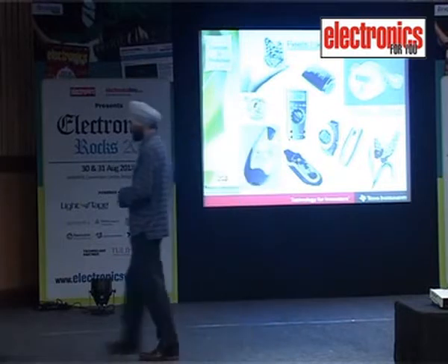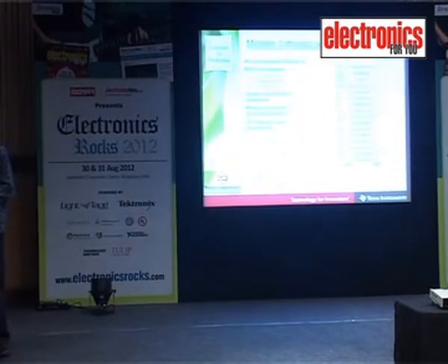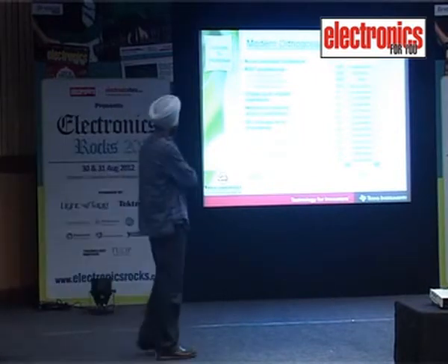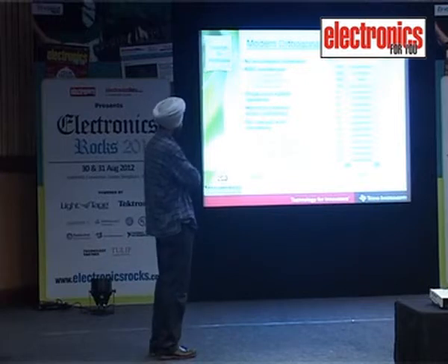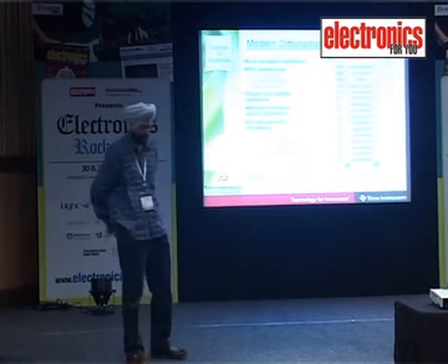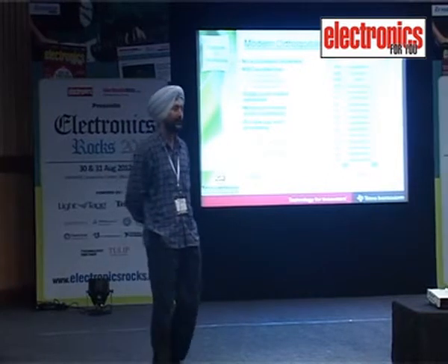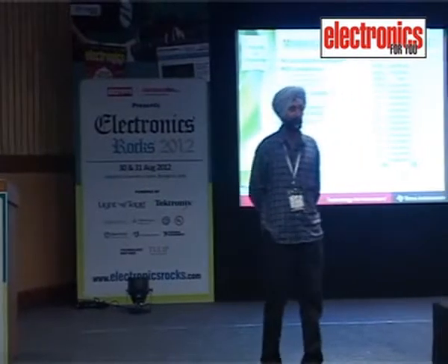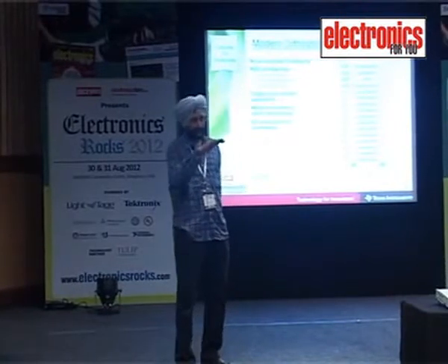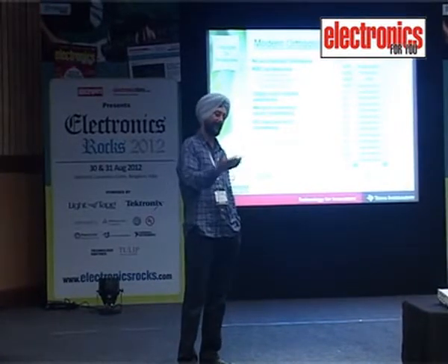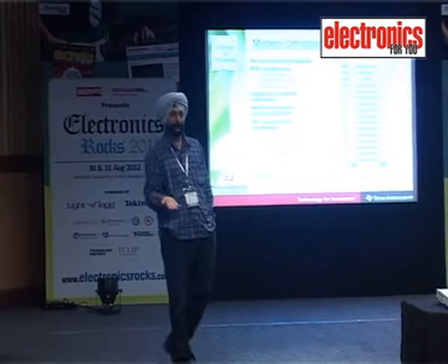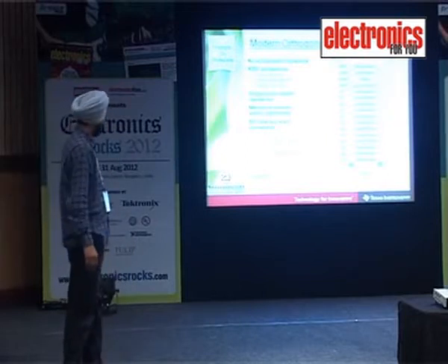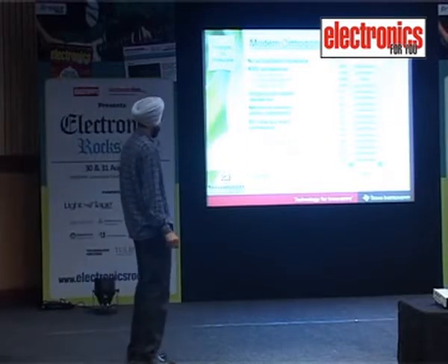Now if you see the modern 16-bit RISC CPU, this is the register set. We have a program counter, stack pointer, status register. So all the flags, like zero flag, carry flag, along with the low power control bits. I mean, MSP430 has multiple low power modes 0, 1, 2, 3, and 4. I mean, instead of simply a sleep mode and active mode, we have multiple low power modes where based on the situation, based on the requirement, we will be able to power down. And these control bits are available inside the status register.